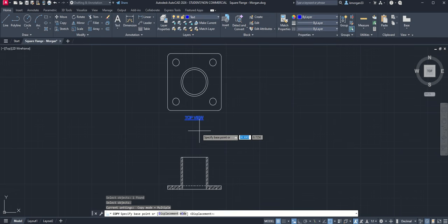And that is a very important place where students get confused. After you click, you don't know what to do. Okay, so what you have to do is just specify any point near that. All you have to do is just click on it. Of course, then it's going to ask you to give another point, and you don't know what to do. You can type something like 90 degrees, or you can click the restrict cursor. That's up to you, whichever way you want to do.